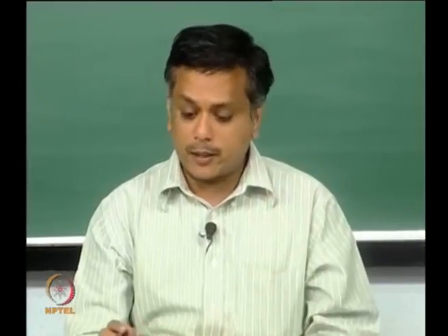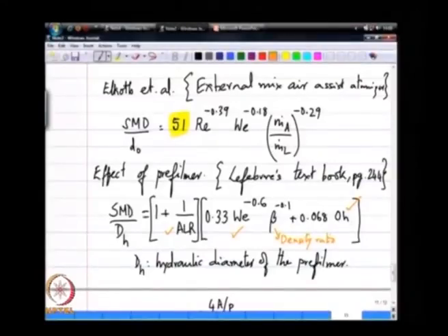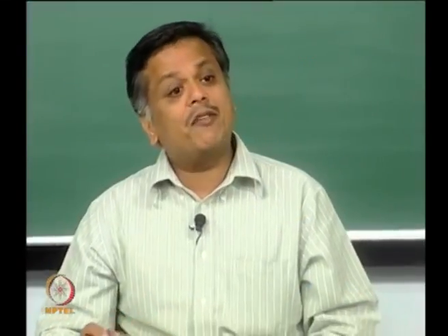And lastly, there is this almost linear dependence on the Ohnesorge number, that as the Ohnesorge number increases, the outer main diameter is going to increase, but the pre-multiplication factor is very small, and notice that this is an additive effect.